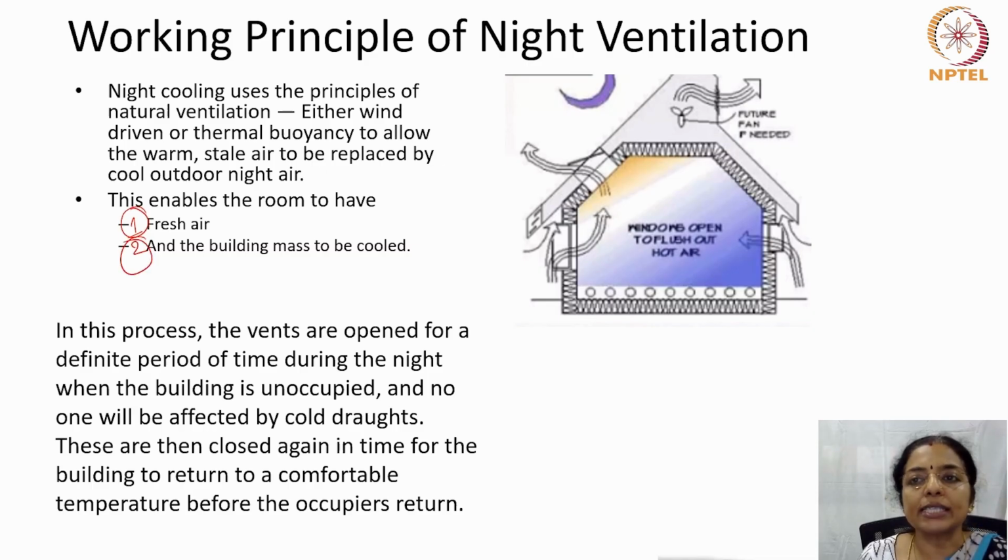In this process, the vents are opened for a definite period of time during the night when the building is not occupied and no one will be affected by the cold drafts. Then these are closed again in time for the building to return to a comfortable temperature before the occupiers return to the building.